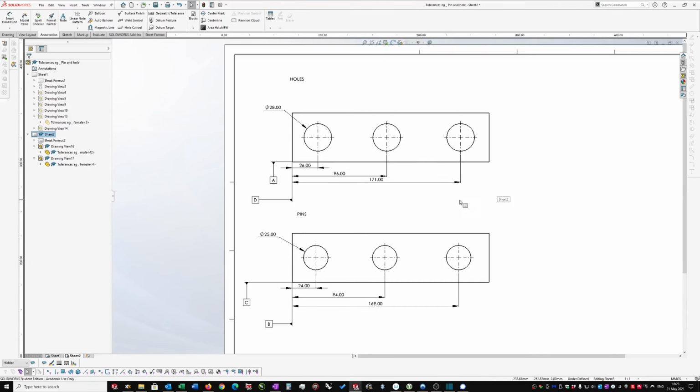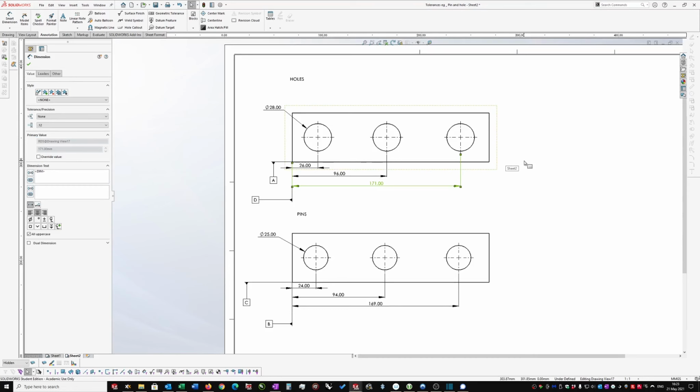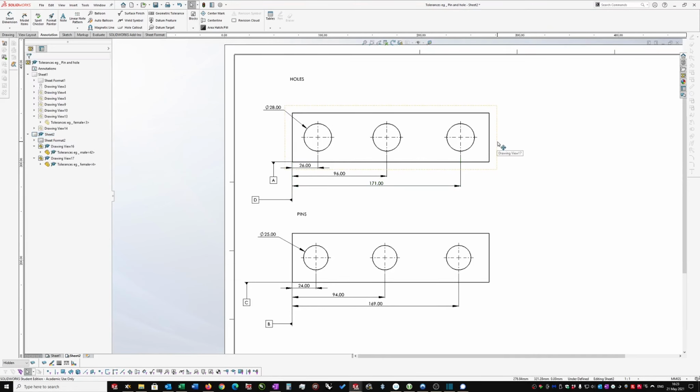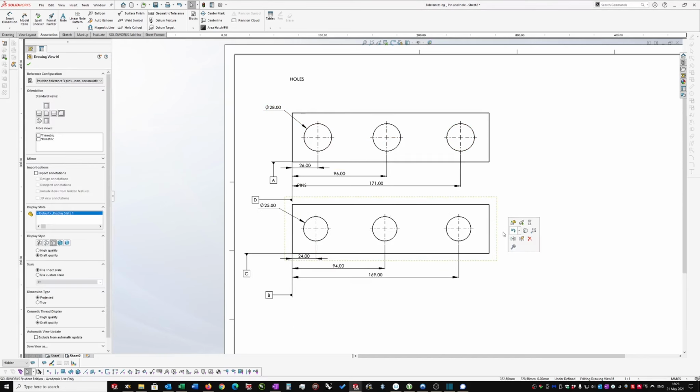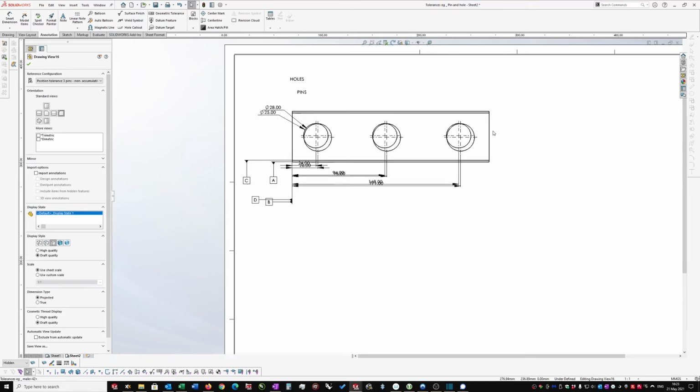Okay, a quick edit. I've updated this. So these don't have the tolerances in them. These are the actual dimensions once they've been toleranced. So this is at the extreme of the one limit and the extreme of the other limit. So that's the extreme maximum positional limit with the extreme size, and that's the extreme minimal position limit with the extreme size. So let's see what happens when we overlay the one over the other.